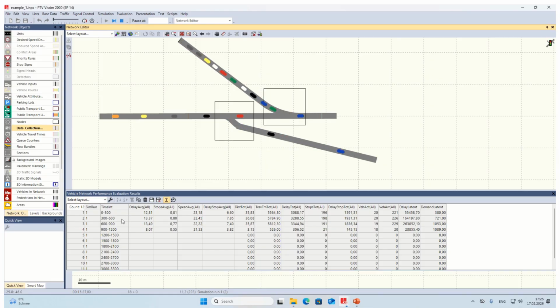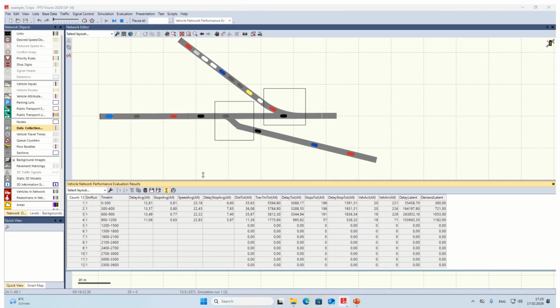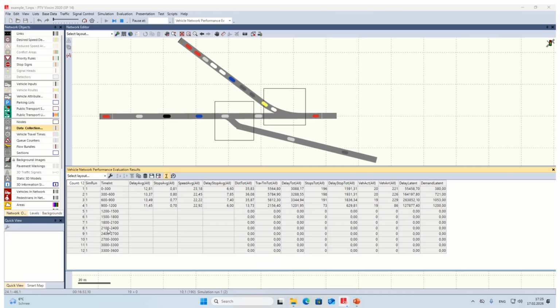So the simulation goes ahead, and by each slice we are receiving the data, but the question is, okay, I have the information by time interval, but is it possible to get some averages or whatever automatically without rerunning and reconfiguring the model or using Excel or whatever? Yes guys, please pay attention that here is a button, show time interval aggregates.